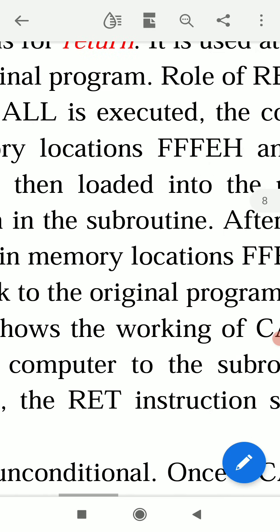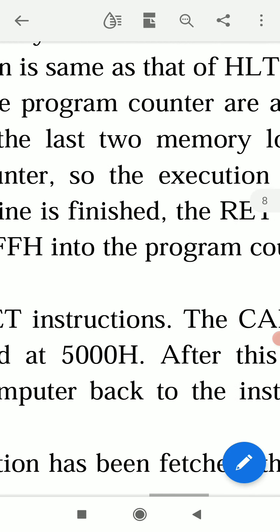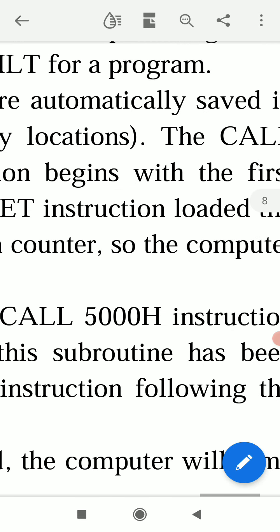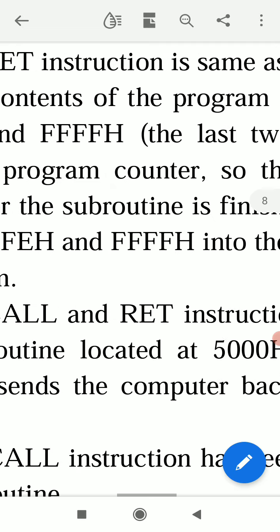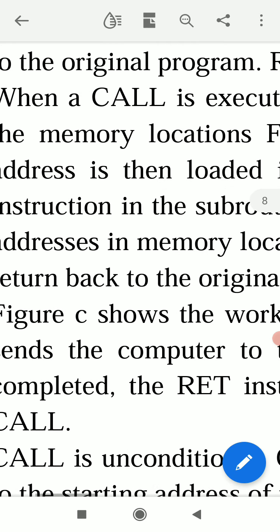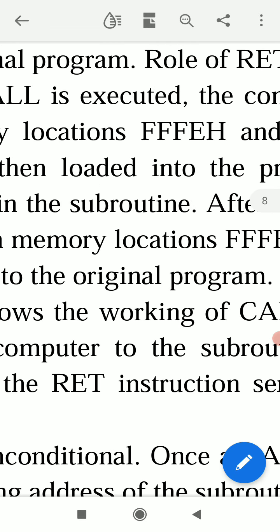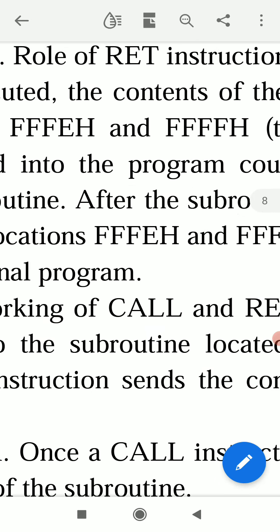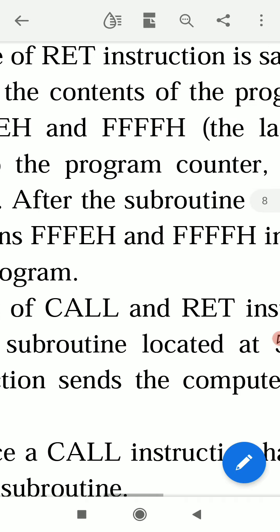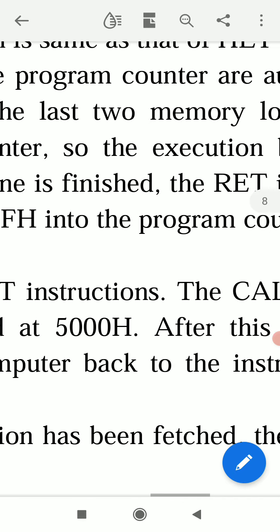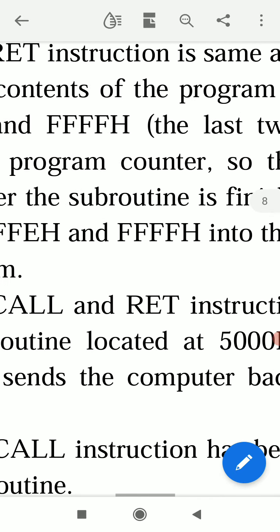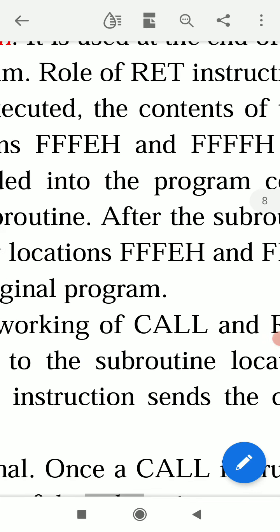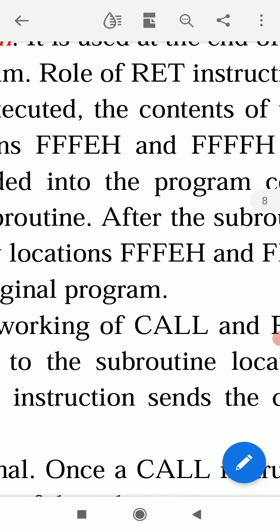When a call is executed, the contents of the program counter are automatically saved in the memory locations FFFEH and FFFFH, the last two memory locations. These are the last two memory locations, FFFEH and FFFFH.